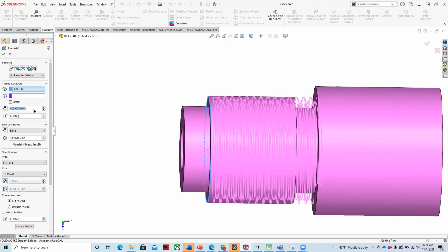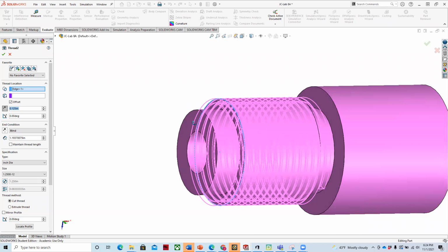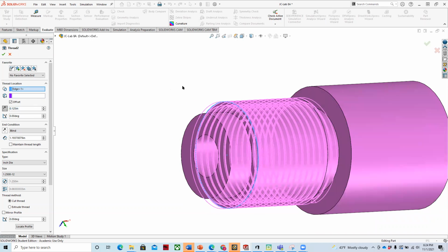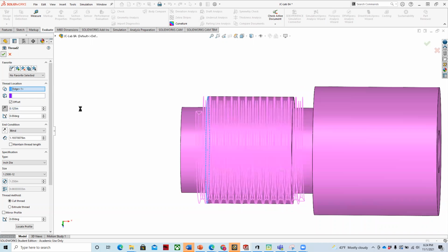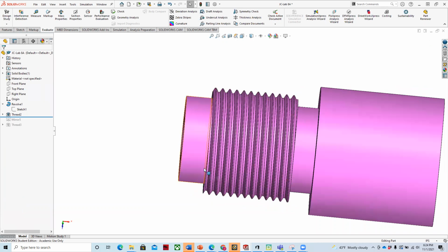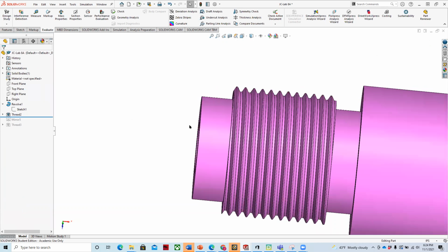And so I'm going to say, let's offset that 0.125, 1/8 of an inch. And let's go the other way, like that. And so that way the thread lands between this little trough here and this one here. And that's kind of what you need when you cut threads on a machine called a lathe. And so by offsetting the threads, that will give the thread a way to begin with the run out. And so that's how I would fix that.